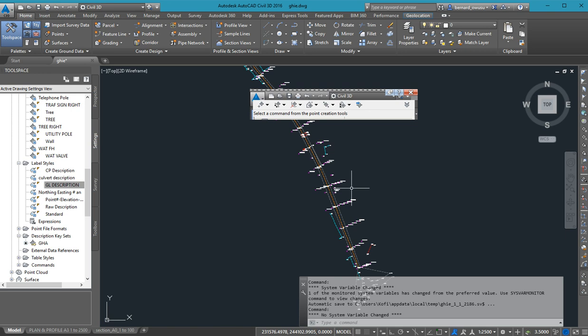But if we have an existing road and you include the river, what will happen is that when it gets to where the river is, there will be a drop. You understand? But that's not what you want, your interest is the road. If there's no existing road, then we want to see the river in terms of the cross section and put it in our profile. I don't know if you are getting the picture.